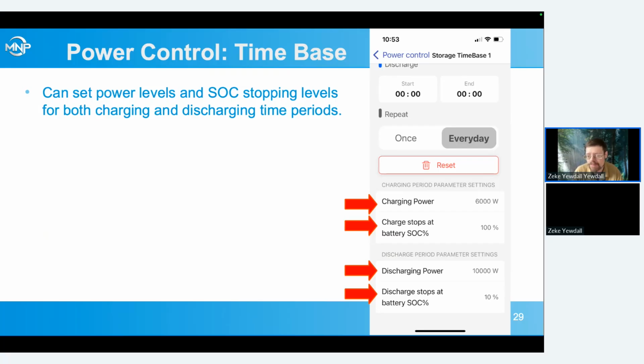For charging power, once we get the firmware updated where you can individually select charging periods for charging from the grid, you could say use self-consumption during a high time of use rate, and then immediately once it goes to an off-peak rate, recharge the batteries back up to say 70%, so you've got some reserve left, but then keep some in there, but not use the grid to completely charge them up and wait for the sun to come out the next day to fully charge them to 100%.